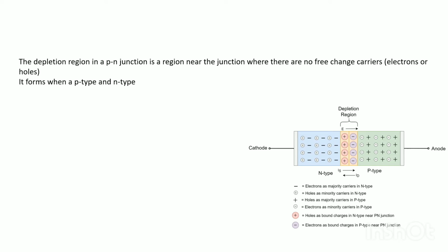You see there is a depletion region, depleted of carriers. When the anode is made negative with respect to the cathode, the diode is reverse biased, and minority holes and electrons near the junction are initially attracted to the negative and positive terminals of the battery respectively.